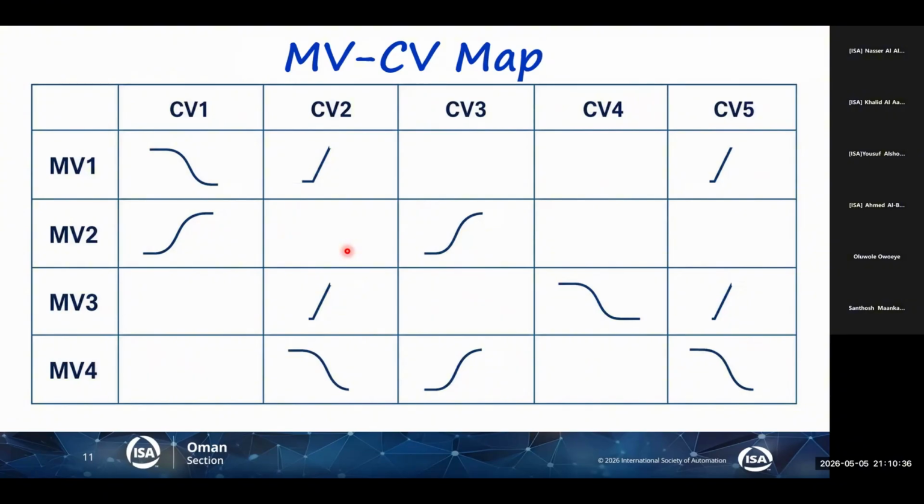which means one MV, and then you see how another CV has reacted. Unlike yesterday, when we heard about the controller output, a valve, for example, and then you watch how the flow is changing. Over here, you might be moving a flow. That is your manipulated variable. And the controlled variable is, for example, quality or a temperature elsewhere.